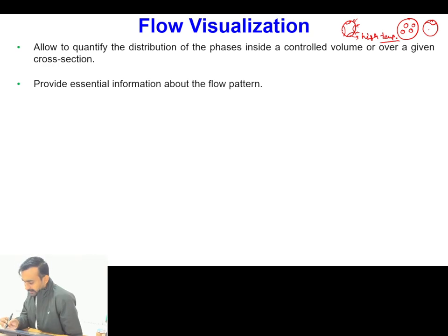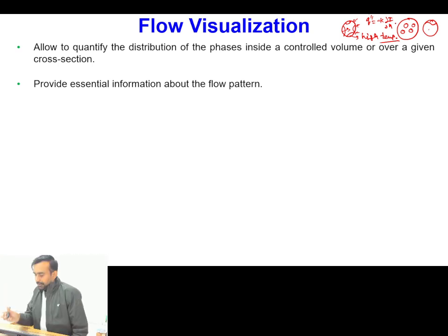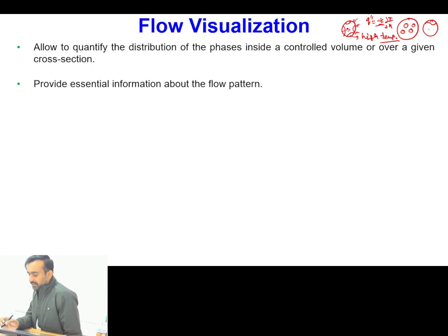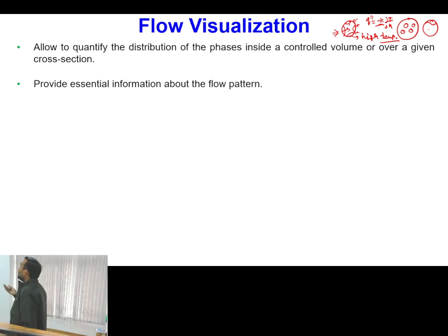Okay, but inside, whatever heat flux is transferring will be a function of thermal conductivity times del T by del N, the temperature gradient in the normal direction. If you have gaseous contact with the wall, then the thermal conductivity of the gaseous phase will be very low in comparison to the liquid phase. So because of this, even if you supply heat flux at a constant rate from outside, the inside fluid will be taking the heat flux at a lesser rate.